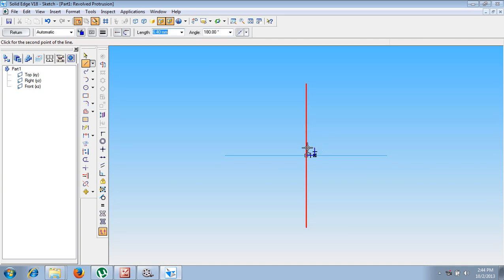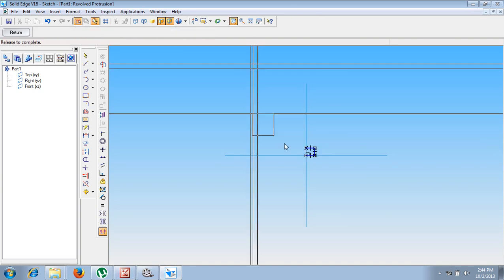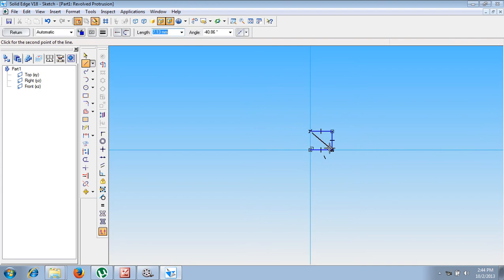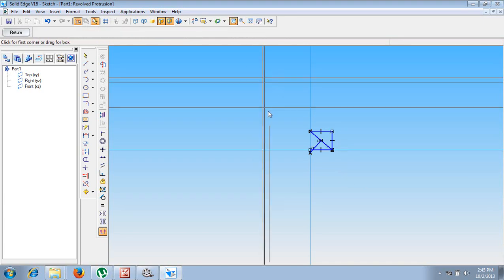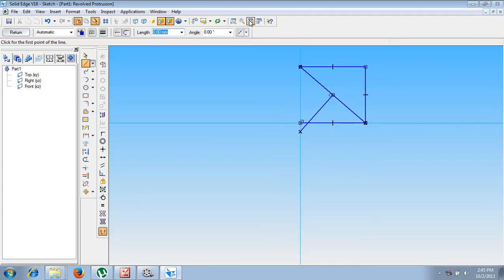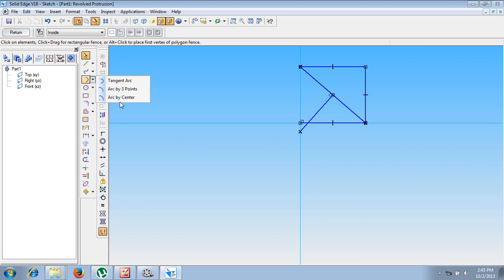Now let me draw a line like this. This is what a required constructional line. Now from here to here you just draw a line. Now using this midpoint, draw a line which is supposed to be the perpendicular bisector like this. Now if you observe this, these are the standards of snap headed rivets. In the same standards, this conical head should also be drawn. Now that is what I am doing here.